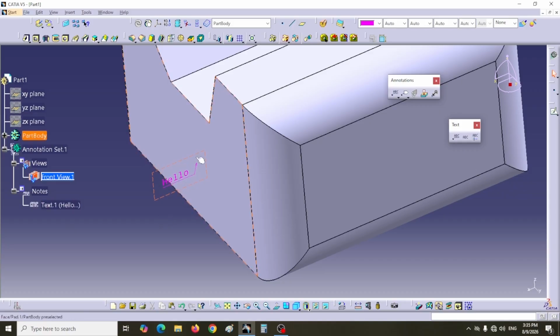If you cannot see them, click on the leader line. A white double-ended arrow appears above the text. With this arrow, you can move the text along the horizontal line. When the text moves, the horizontal line also becomes longer or shorter.